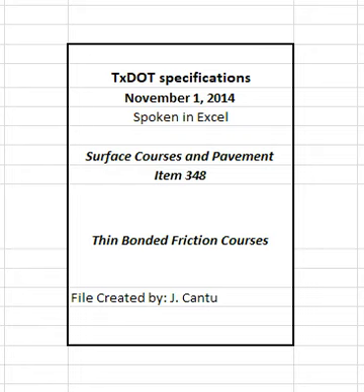5.1 Membrane. Unless otherwise noted on the plans, membrane material will be measured by volume. Membrane material will be measured at the applied temperature by strapping the tank before and after road application and determining the net volume in gallons from the distributor's calibrated strap stick. The quantity to be measured for payment will be the number of gallons used, as directed, in the accepted membrane.